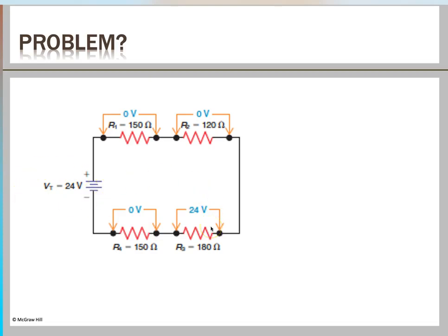That means just by the voltage across the resistances, we can detect that this side of the series circuit is open. So you can say R2 is open, because we are seeing the supply voltage across these 2 terminals, and the rest of the resistances will receive 0 voltage.